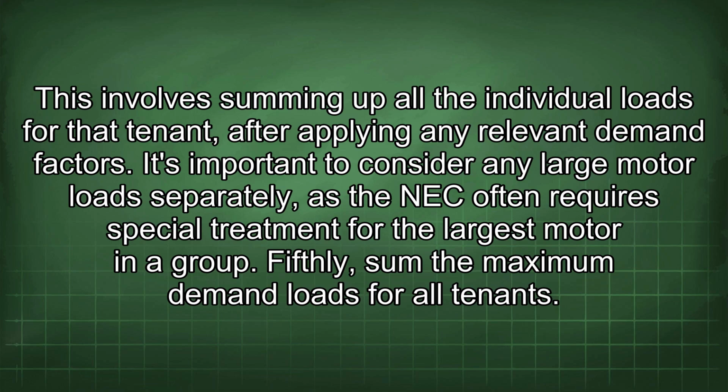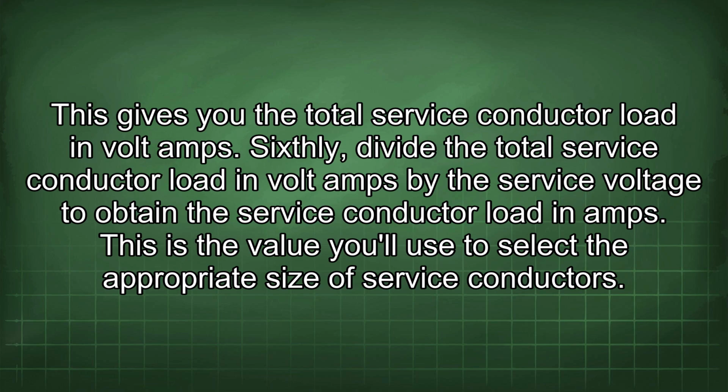It's important to consider any large motor loads separately, as the NEC often requires special treatment for the largest motor in the group. Fifthly, sum the maximum demand loads for all tenants. This gives you the total service conductor load in volt amps. Sixthly, divide the total service conductor load in volt amps by the service voltage to obtain the service conductor load in amps. This is the value you will use to select the appropriate size of service conductors.